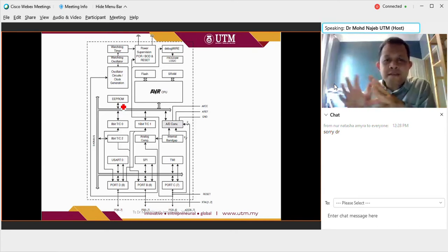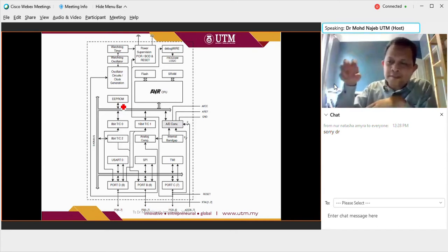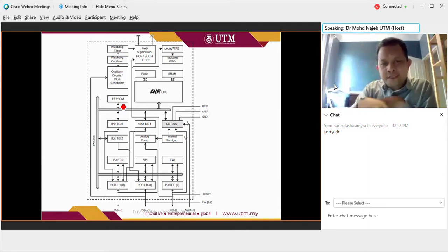So they use light. You have to remove the ROM first, put it in something like a small UV cabinet, then you expose it to UV for some time, then it's erased. So imagine at that time, you need to remove your IC, and if your UV unit is blown, you have to replace the lamps, things like that.